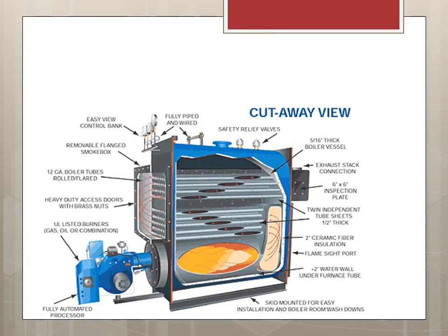So this is an example of an industrial boiler. If you can notice here, these are fire tubes, where the fire and flue gases go through the tubes, and the water is washed around them. These are the main components, and you can see it looks like a bigger gun burner over here, and these are my relief valves, and we have two just for redundancy and safety.